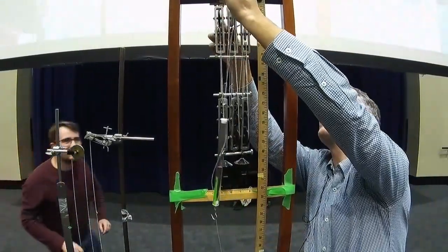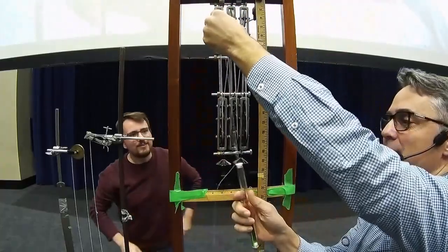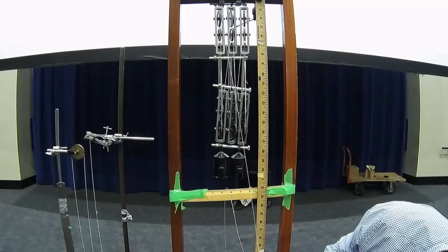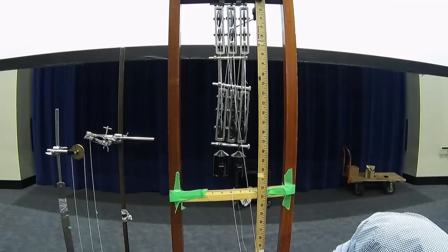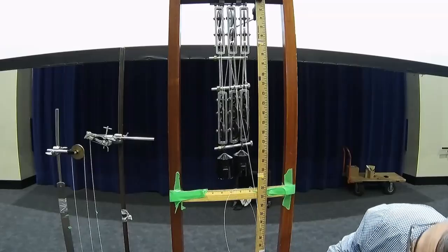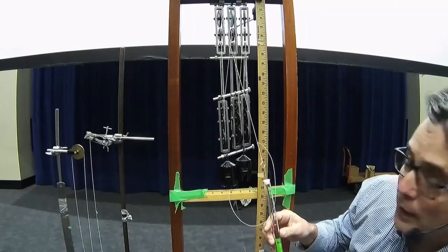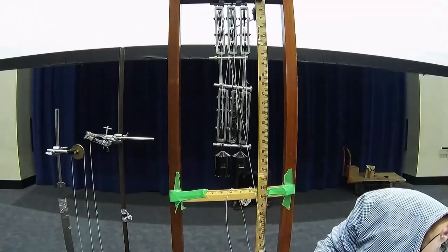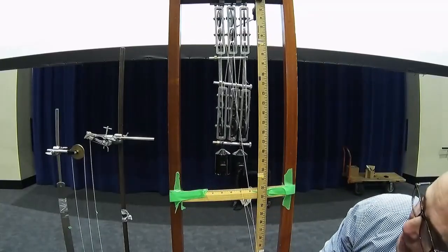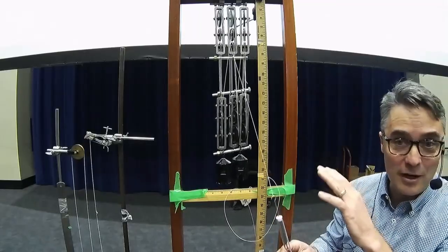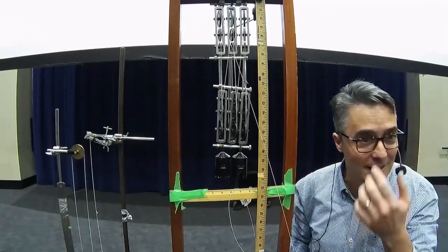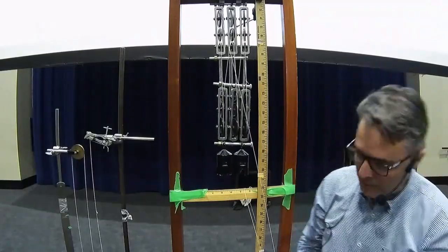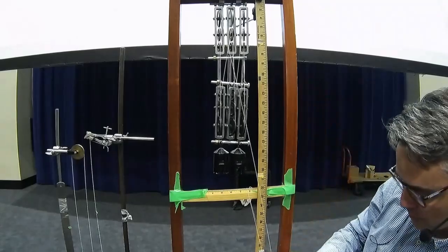Now I got a bunch of friction because it easily falls off. Okay, so now I can pull it up, and I'm providing an input force of almost 1 Newton. Actually it looks more like 0.8 Newtons to lift 1 kilogram. So that's like 10 Newtons on this side, and I'm putting in maybe 0.8 Newtons on this side. So that's a system where you can imagine, I think that sometimes people use this in theater where they're trying to lift a curtain or some sort of prop. You can use a lot of pulleys to reduce that input force.